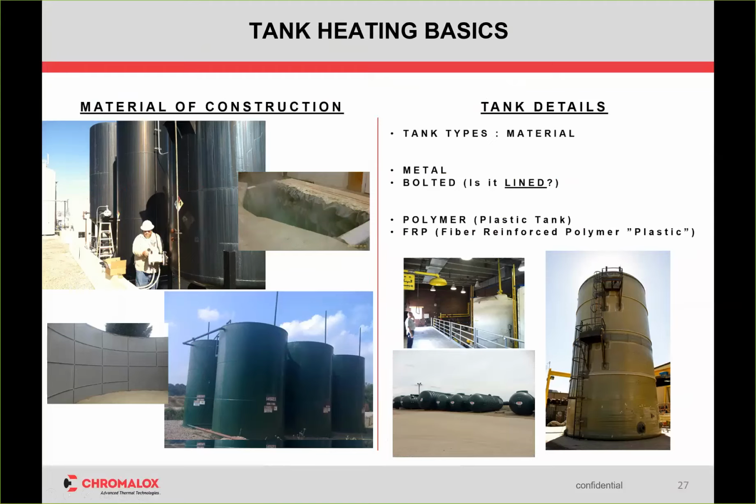One step further is we're getting polymer and fiberglass requests daily now. And years ago, we didn't want to put an electric heater in there, but we do it a lot now. There's just a couple things to consider. One came up from last week's presentation, and thank you to Scott Grogan for mentioning this. A lot of salespeople have started commonly just offering a 1-inch smaller bundle diameter, so it fits into the tank.